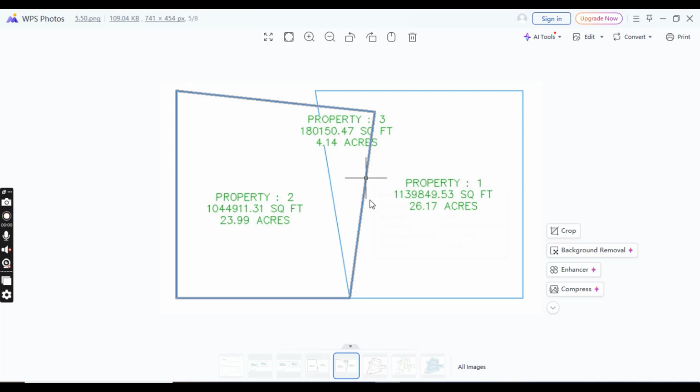However, through this import, the data for right-of-way lines might not fit the desired intent of using the tool, since they will be segmented at every place where they interact with a property line. This makes labeling more difficult and may require additional edits to the data to fit your design intent.